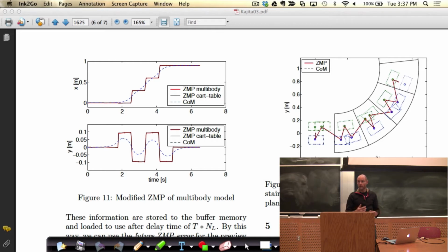So they're related, obviously. You want to keep your center of pressure in the middle, and that implies that your center of mass stays near the middle. I should say center of pressure. So you're really planning on the center of pressure trajectory, and then using the equation tells you where your center of mass has to be going. Yes. But you want the solution that has the property that the center of mass stays within your support polygon. Yep.